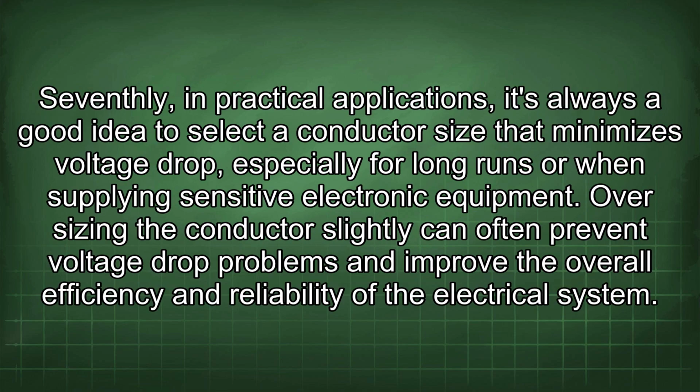Seventhly, in practical applications, it's always a good idea to select a conductor size that minimizes voltage drop, especially for long runs or when supplying sensitive electronic equipment. Oversizing the conductor slightly can often prevent voltage drop problems and improve the overall efficiency and reliability of the electrical system.